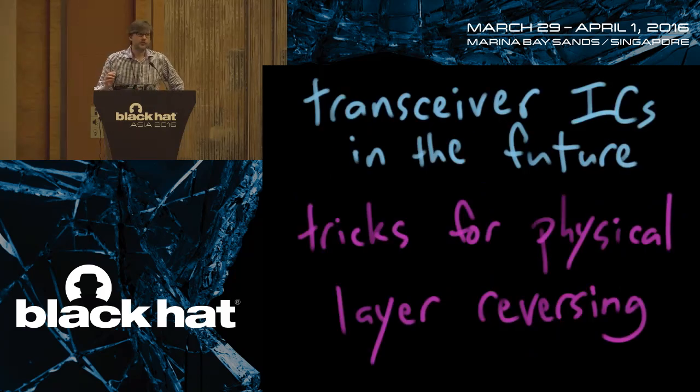But we might also have better tools for reverse engineering just using the transceiver ICs in the future. In particular, I've talked with some folks about some tricks we could use with things like the YARD Stick One to do reverse engineering of the modulation and the data rate. But primarily those tricks are things like: try a whole bunch of different modulations and see what works, try a bunch of frequencies, try a bunch of data rates, or oversample and then figure out what the periodicity is. It's kind of hackish. And so in the long run, I think SDR will win.